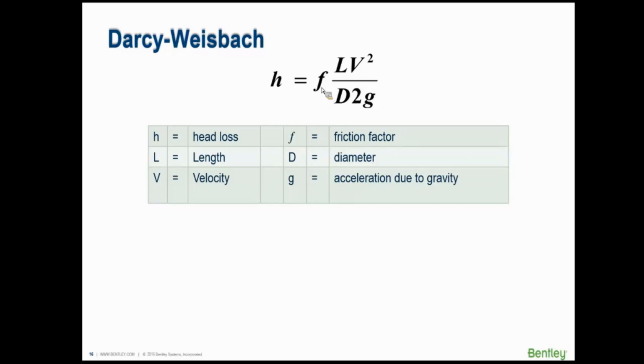Well, the people who were studying this had a lot of trouble. Darcy-Weisbach came up with this equation about 1850 or so, and for the better part of the next century, a lot of research was done on what F is, because you would measure F in one situation and get a value, measure it somewhere else and get a different value. It was a very difficult problem that people looked at for years.